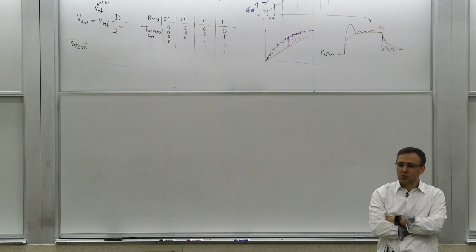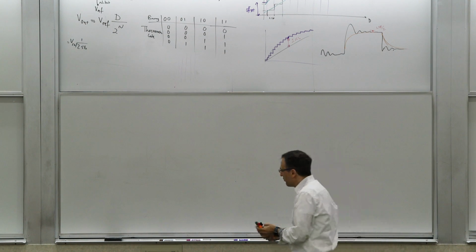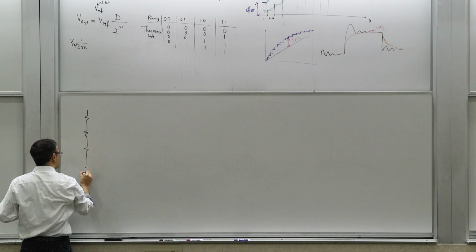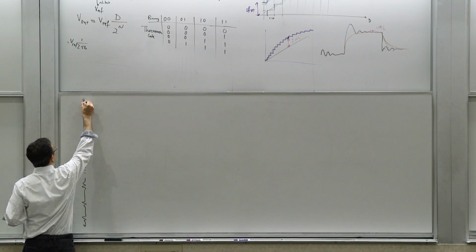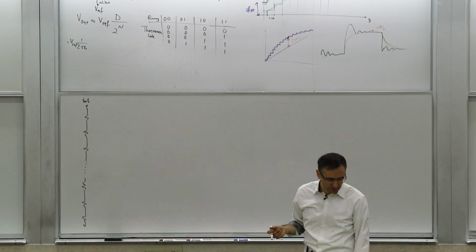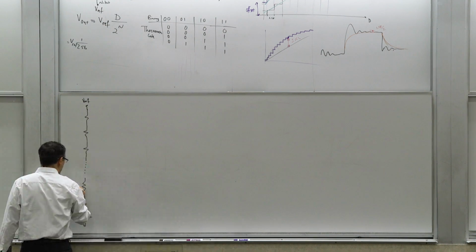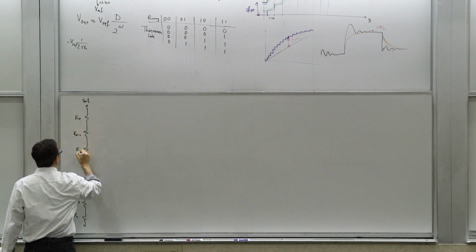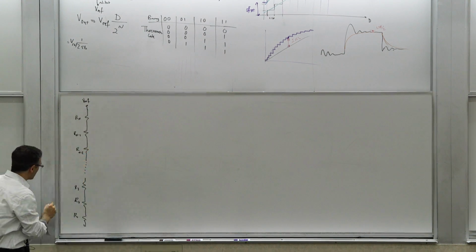Let's say you have resistors and switches, right? So how about if we have a resistive divider ladder? You take your Vref and put it across a resistor ladder, a bunch of series resistors. You have resistors R1, R2, R3, all the same value, let's say, all the way to Rn minus 2, Rn minus 1, Rn. So if you look at the voltages of these nodes, right?